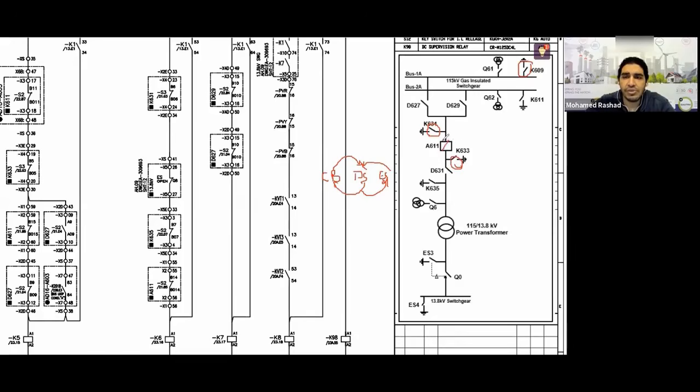As long as this breaker is open, and this breaker, sorry, here it is. This breaker is open, right? And this disconnector switch is open, so I don't care if this one is closed or not. This disconnector has nothing to do with that disconnector. You might ask me, why check this one? Check this one, because if it was closed, it would cause this disconnector and its closure to create coupling between the bus bars. But if this one is closed, it doesn't matter to me at all, even if this one is closed. Isn't the breaker here already open? It's not a problem, it doesn't matter to me, it won't affect anything.